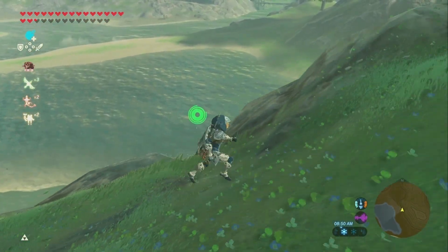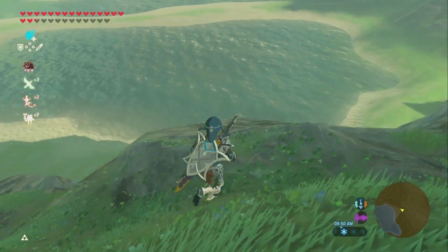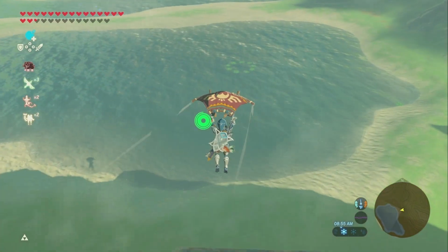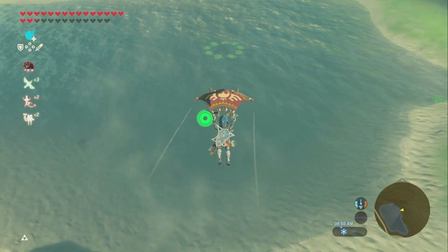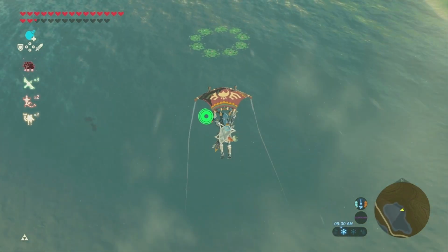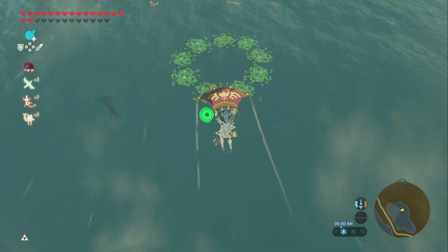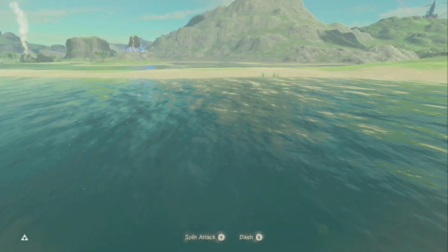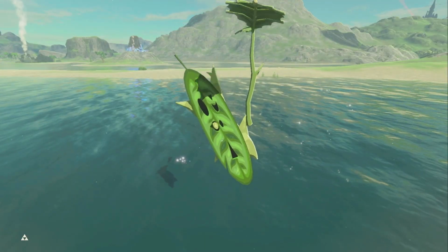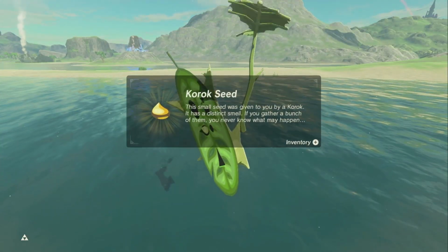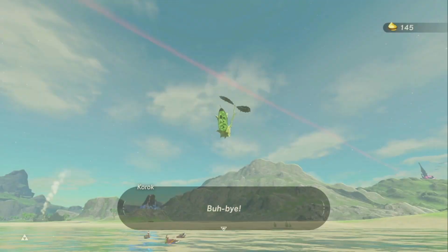Implications. The baffle may fall into the burner, affecting burner operation and reducing the efficiency of the system. A missing or displaced baffle will allow exhaust products to move too quickly through the tank. This increases fuel consumption.